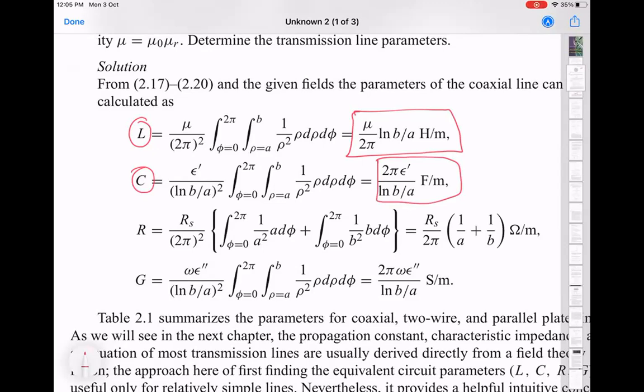It's the ratio, which basically means it's the gap. Right? It's not really the gap because it's not the difference, but it's the ratio. But that's because that tells you the spacing between the two conductors. So inductance per unit length is proportional, of course, to mu, and it basically goes as log of B over A.